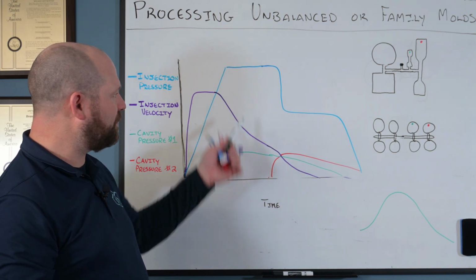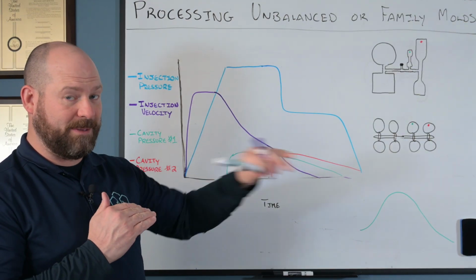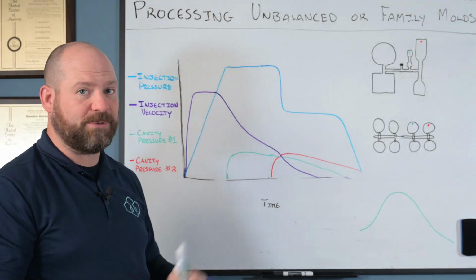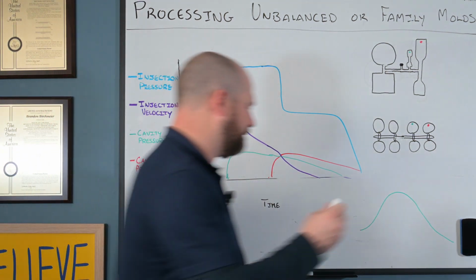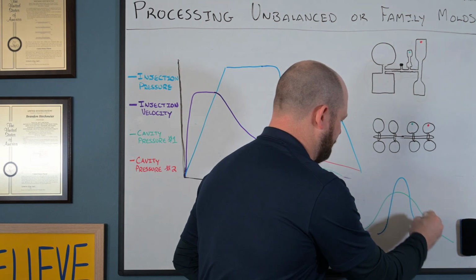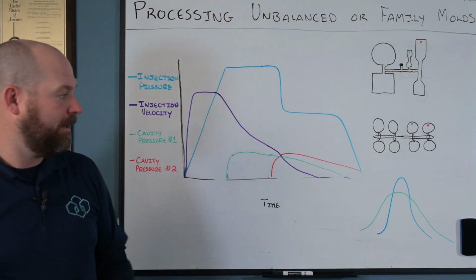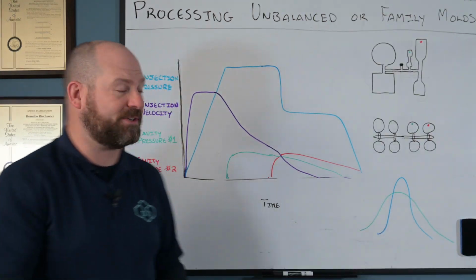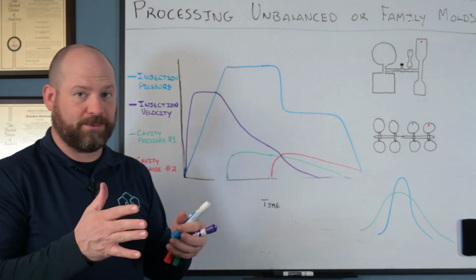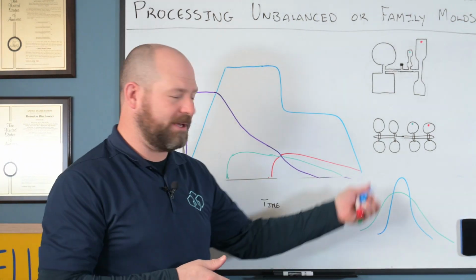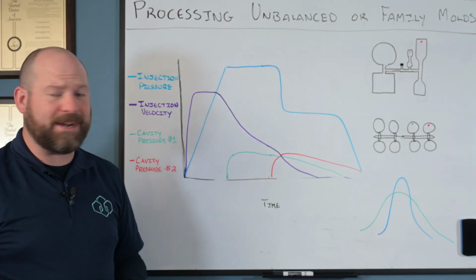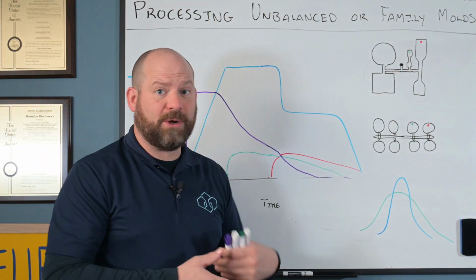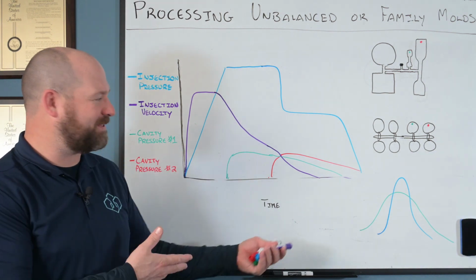However, taking this approach, allowing pressure to be maintained, the delta between your peak pressures and those part weights will narrow. Okay, and that's what's going to help your process. You're going to be bringing those weights closer to each other. So you think about your weight distribution across these cavities. That'll apply to your dimensions. Also, the tonnage required to process these parts.